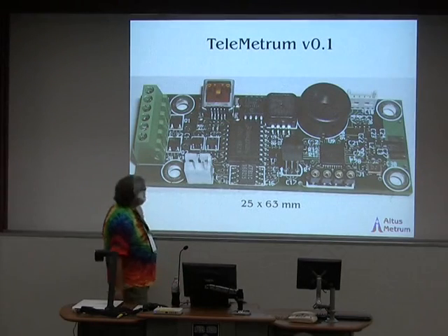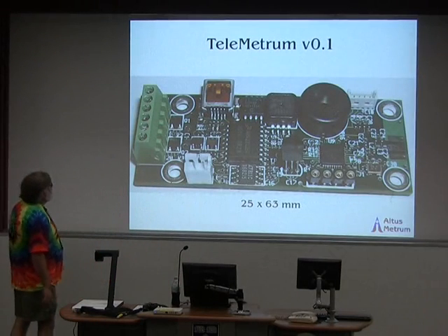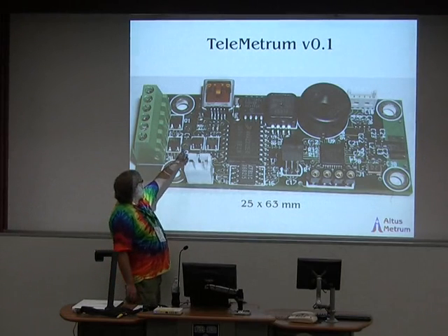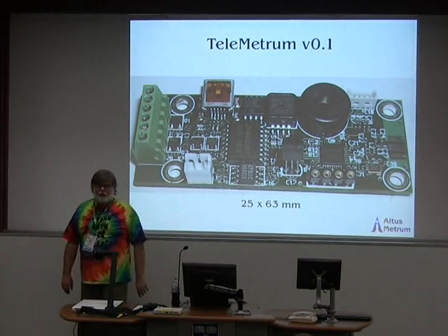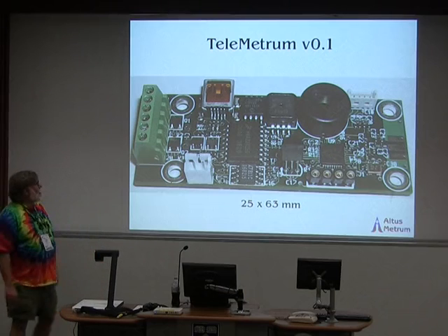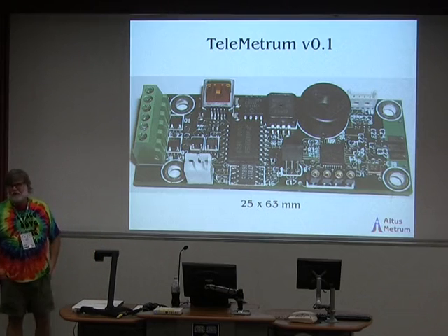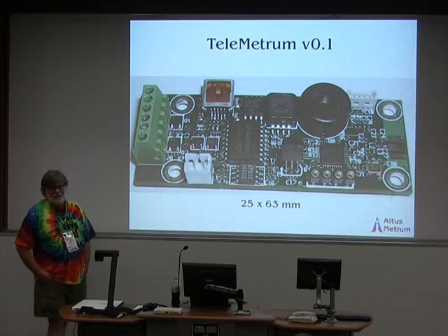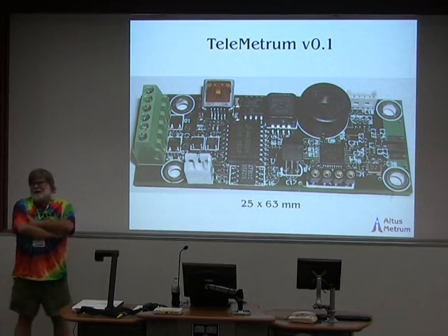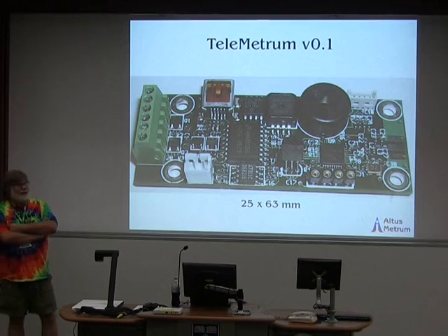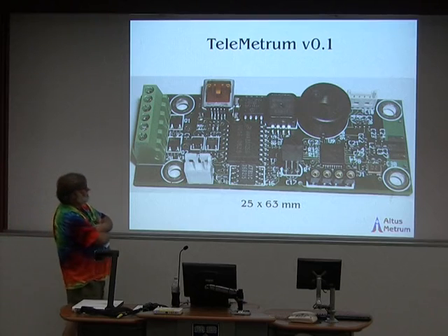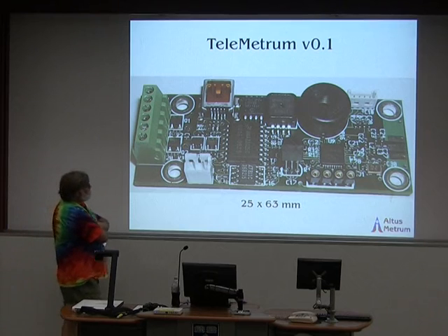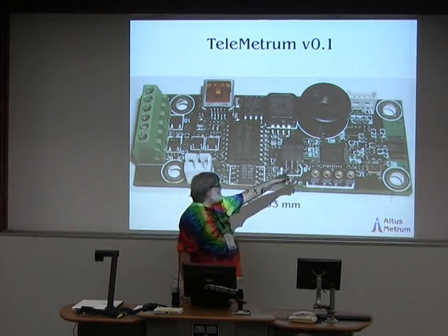But this is the cool picture. That was the board, minus one really annoying part, which these two holes were for the leads of a 1,000 microfarad electrolytic cap to be used in the pyro firing circuit. And that part ended up being a little bit of a hassle, because the mechanics of trying to keep a big electrolytic cap from moving around when you're hitting something with a lot of acceleration and vibration is kind of interesting.